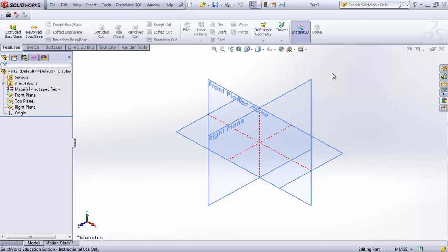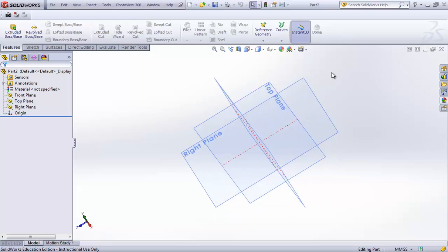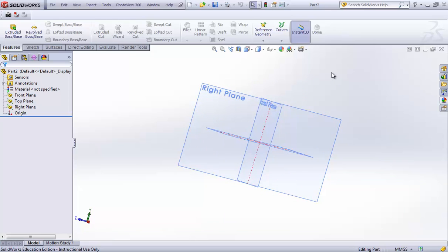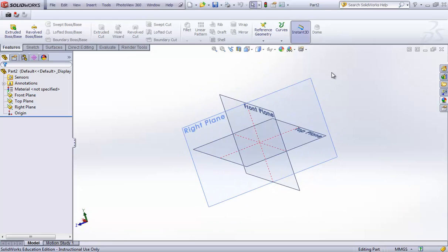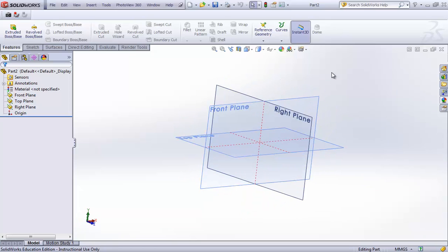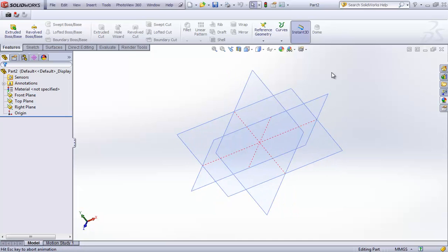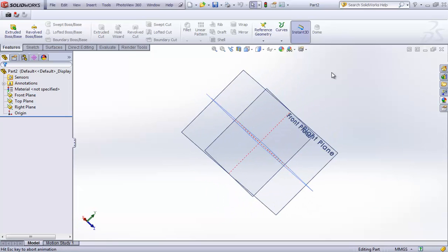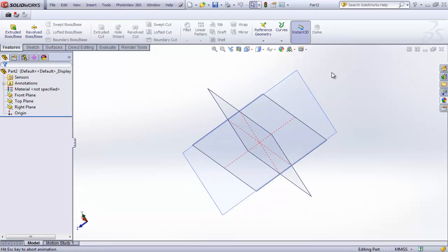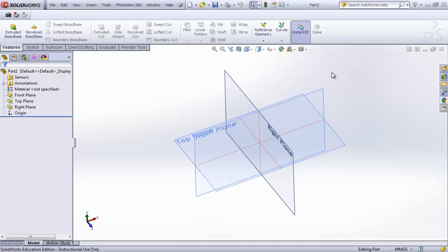A second way, you can use your arrow keys on the keyboard. So I'm trying my up and down arrow keys, and the left and right arrow keys, and that allows me to rotate an object. I can see my reference plane rotating. Secondly, we can hold down shift and try the arrow keys, which will rotate the object by 90 degrees.